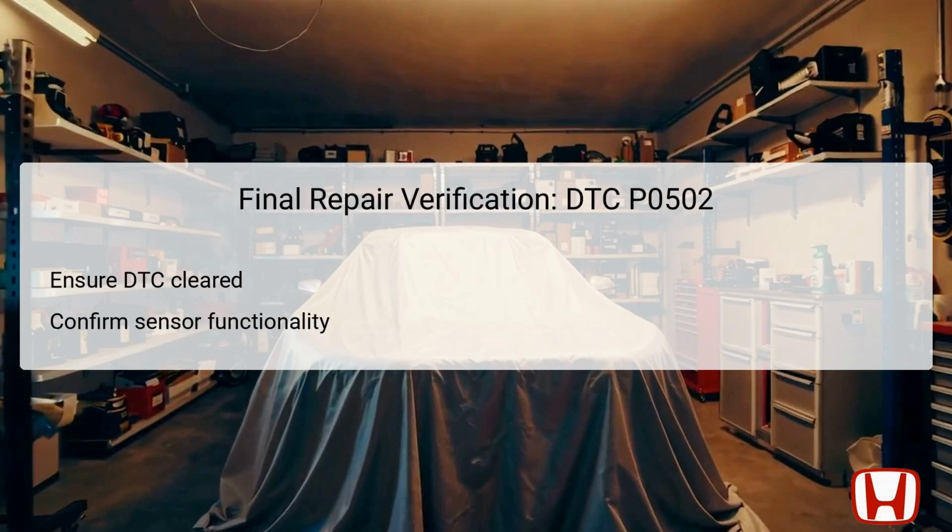Final repair verification is imperative to ensure that all remedial steps taken in response to DTC P0502 have been successful. The first action is to confirm that the DTC has been cleared from the system, indicating that no lingering issues remain. Following this, verifying the functional status of the CVT speed sensor is vital to ascertain whether the root cause has been addressed comprehensively. A diagnostic tool, such as the HDS, should be utilized to perform a function test and confirm that no new DTCs arise, demonstrating that the sensor communicates effectively with the PCM.